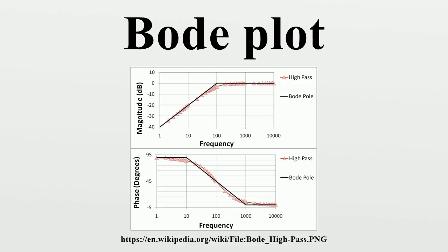In summary, subjected to an input with a given frequency, the system responds at the same frequency with an output that is amplified by a factor and phase shifted by an angle. These quantities, thus, characterize the frequency response and are shown in the Bode plot. Rules for handmade Bode plot.